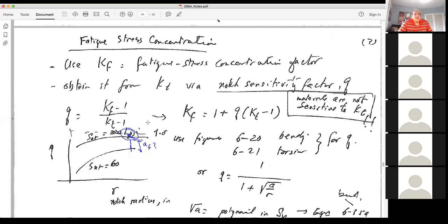So we have a modification of the rotating beam endurance limits here. The other thing is that when you go to a shaft, the shaft, of course, is going to have different sizes, right? Like in our design project. So we have to use the corresponding size factor, and the surface finish will be different. It'll be ground and machined or honed, depending on how expensive the piece is. And therefore, we could apply all of these factors, right?